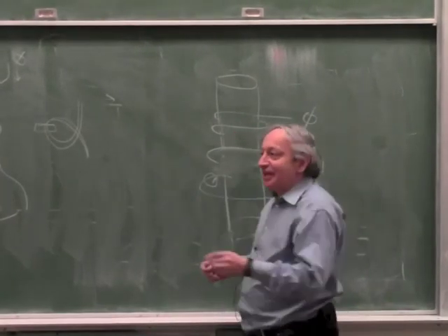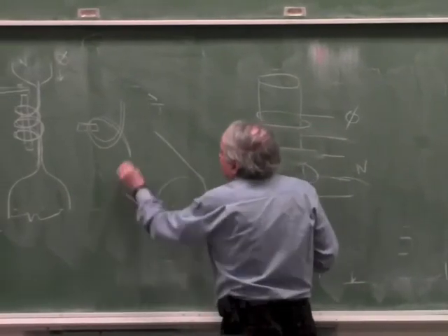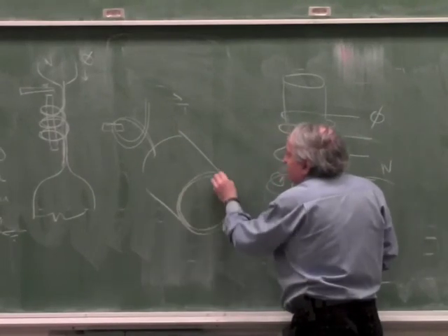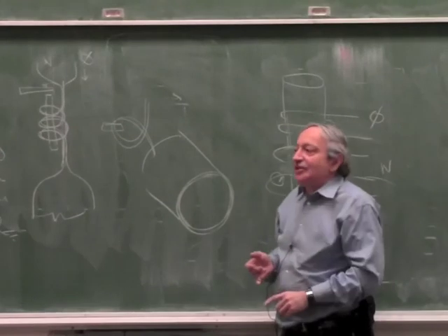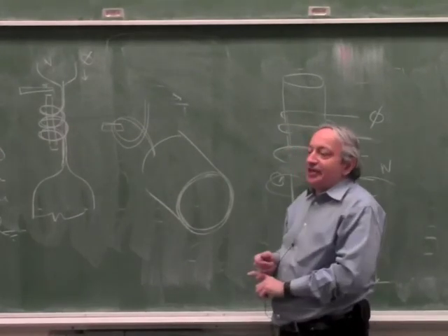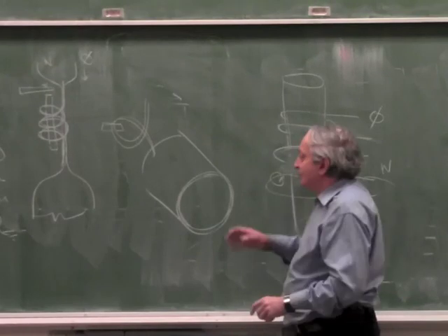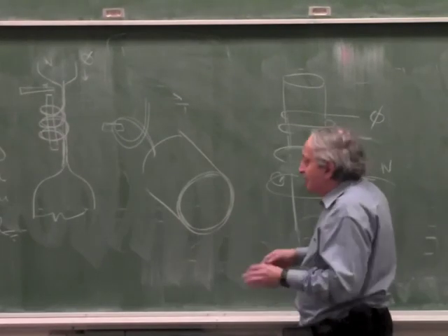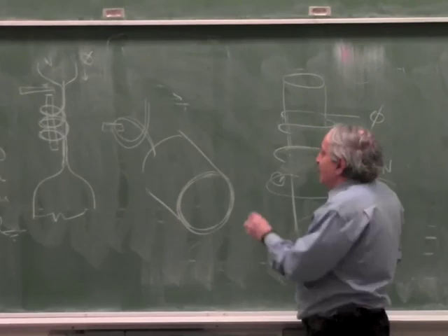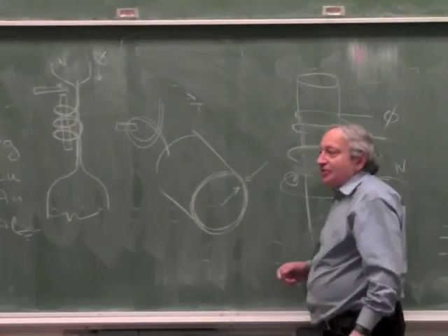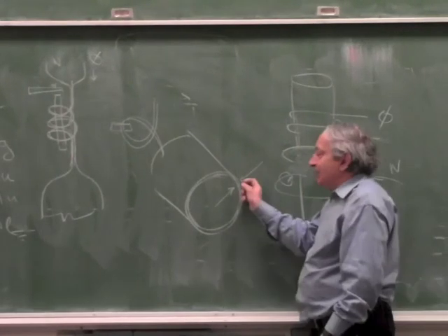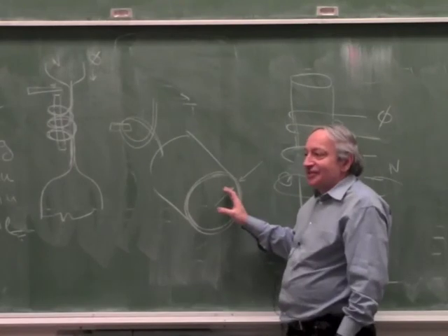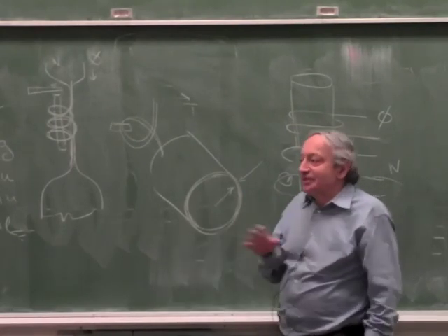So remember, at high frequencies, when you have a conductor, the current doesn't flow through the whole conductor. It only flows on the skin, and the depth of the skin is a function of the frequency, of the dielectric, and of the magnetic constant. Since metal is not dielectric, it's not magnetic, it's basically just a function of frequency. When you plug in the numbers in the formula, if you have a copper conductor and you're dealing with a gigahertz, the skin depth is going to be only microns. So all the current is carried just on the surface. So you put a thicker conductor, it doesn't help at all.